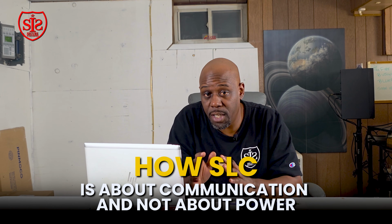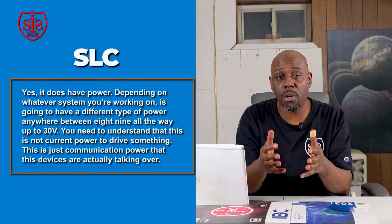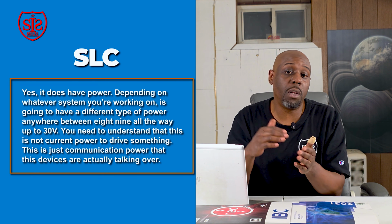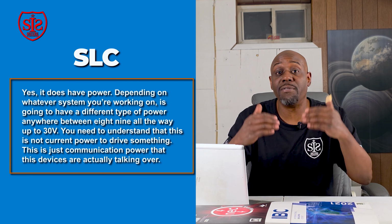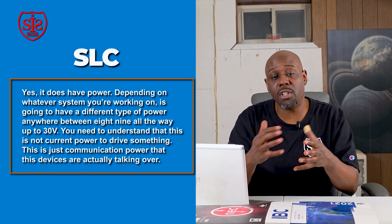So let's start with the first principle: SLC is about communication and not about power. Here's the mindset shift I want you to have for you technicians coming up. The SLC, yes, it does have power, and depending on whatever system you're working on, it's going to have a different type of power, anywhere between 8, 9, all the way up to 30 volts. You need to understand that this is not current power to drive something. This is just communication power that these devices are actually talking over.